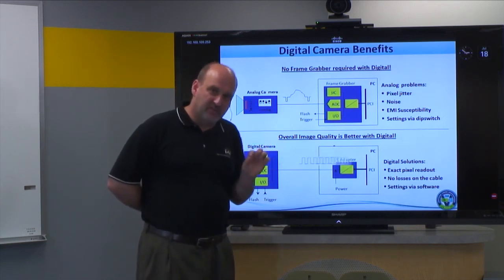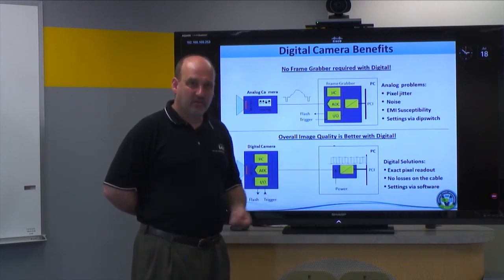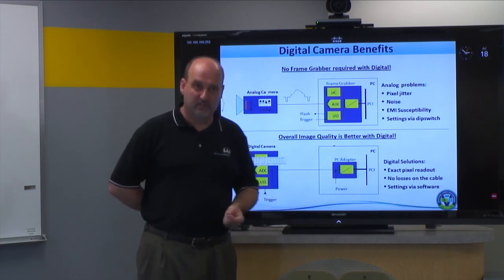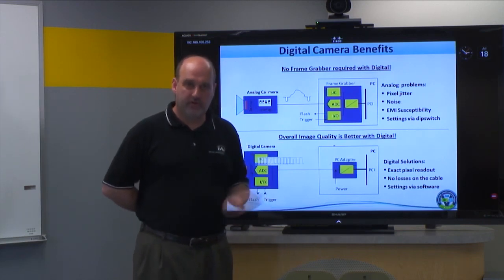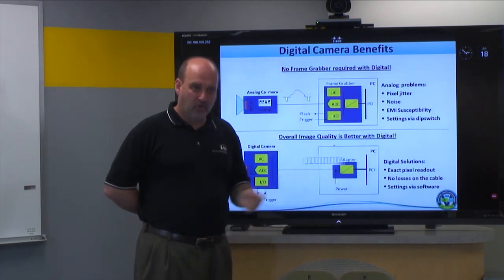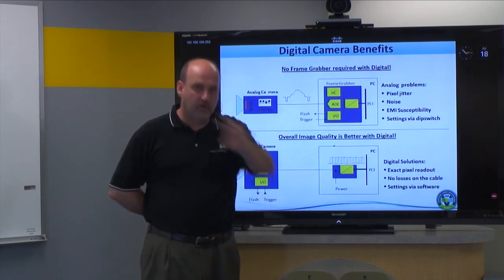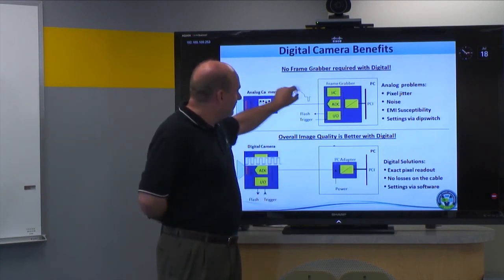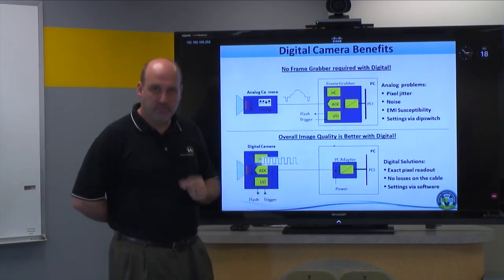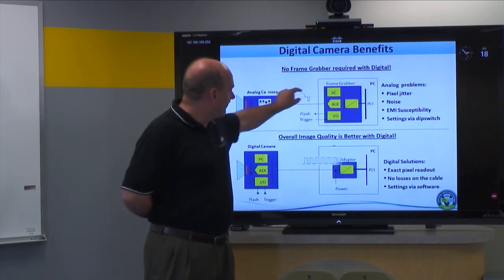That means if I pick up as little as 10 millivolts coming down my cable, those 10 millivolts are a substantial portion of that 700 millivolt signal, and that's where you see noise or interference. If you've ever seen TV and you got a bad signal off your antenna, or if someone started a motor or something noisy around it, you see snow on the screen. That's because it's making spikes in here, and those spikes are being interpreted by the receiving device as a bright pixel or a dark pixel, and that noise is very inherent on here.